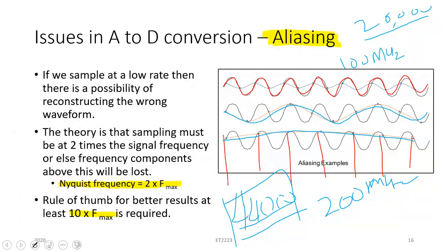So this is something that you may observe when certain music is played through certain telephone systems, like waiting sound, or when you call a call center, it may be playing some music and it may sound a bit odd because it is impacted by the issue of aliasing, because the original sound is beyond half the sampling rate there.